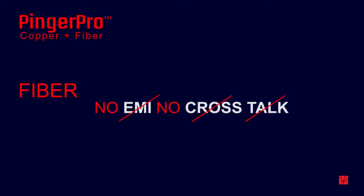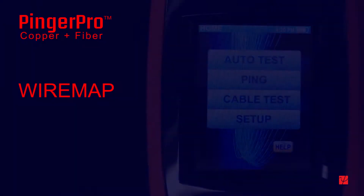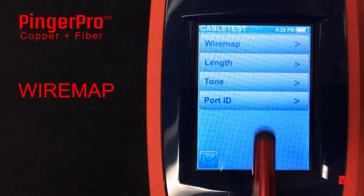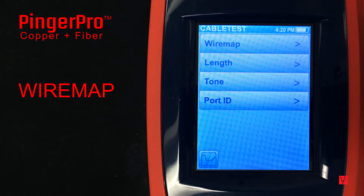Fiber does not require multiple conductors like copper and does not emit EMI, eliminating crosstalk. This reduces fiber testing requirements to mainly an attenuation loss test. New installations should always be tested for correct wire map to ensure the link will work when devices are connected. Additionally, patch cables can be subjected to hard use and develop problems that can be identified with a wire map test. Pressing the cable test button on the home screen brings up the cable test menu.